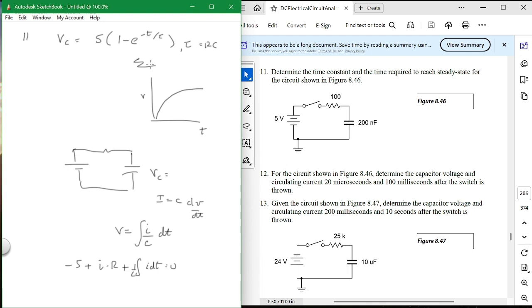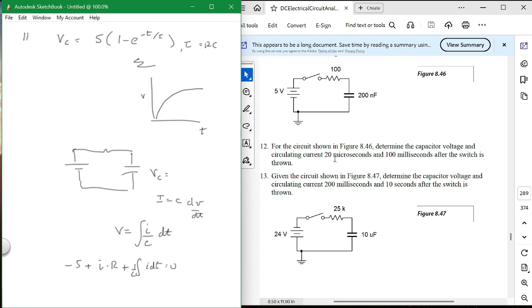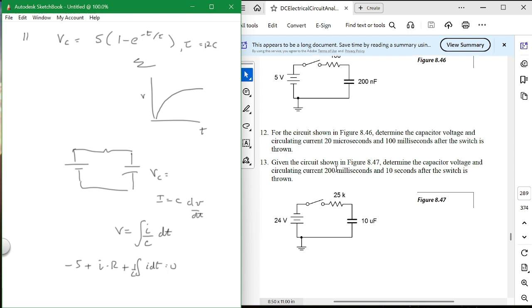But that's what it is. So if you're interested in that part of it, that's what it is. If you're not, forget about it. Just take this and run with it. But you're looking as a detective for this particular set of circumstances, and you're going to write this. That's very interesting, but it's based on this: a first order differential equation, with either a capacitor or an inductor, but not both. So with a capacitor, there it is: voltage, 1 minus e to the minus t over tau. Tau is equal to RC. The next chapter is going to be L over R. So you're going to have these little variances, but basically it's the same thing. Instead of V, it's I. It's the same thing. What about this one?